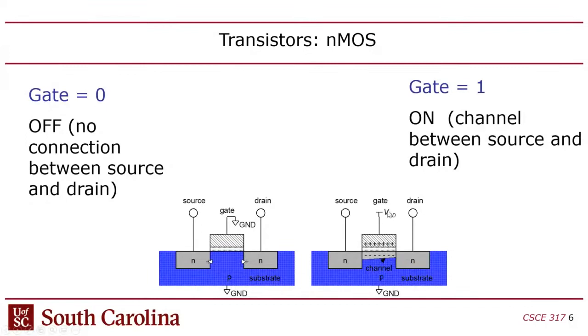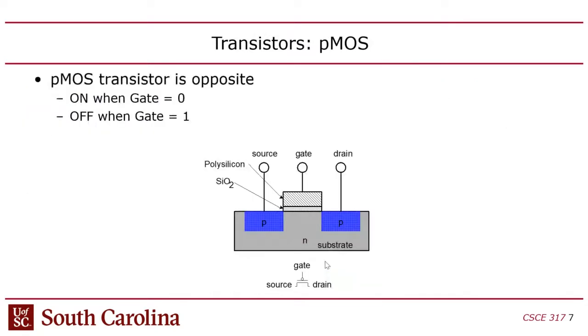And so the voltage between the gate and the channel is going to depend on the source and the drain voltage, or the voltage between them, right? So it's no longer a capacitor relative to ground. It's a capacitor relative to whatever's going through the channel. That's a very subtle point, but that's a very important aspect of how MOSFET transistors work. And I'll come back to that in a minute.